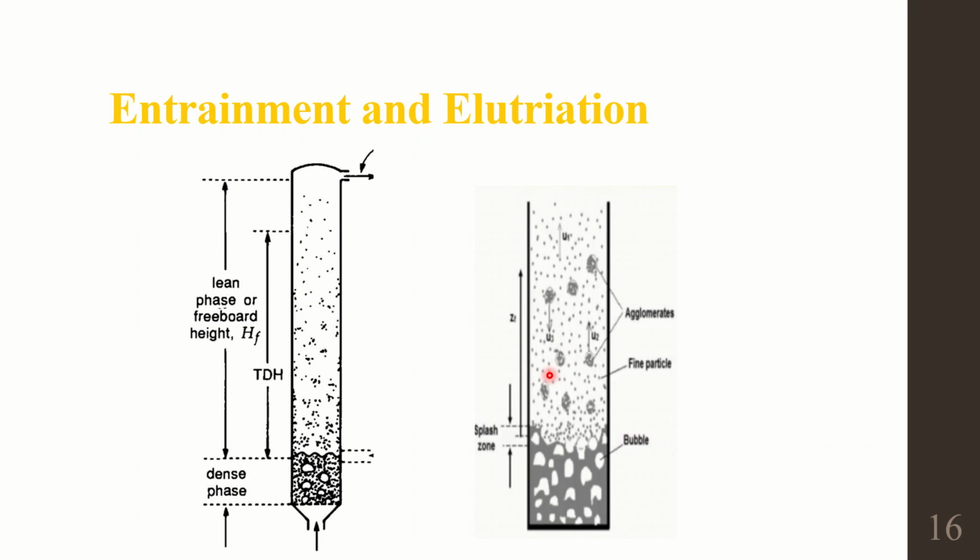For modeling of these beds, one set of particles would be moving up, and after that they would be falling down. These terms, like agglomerates and fine particles, were used in Kunii's, I think it is the bubble coalescence model or something. So it is a part of understanding how the solids weight fraction would be varying, and how the solids would be carried over if it is a reaction, or a process involving solids carryover. It becomes necessary that we allow recirculation to take place, so that we are not losing the valuable materials.